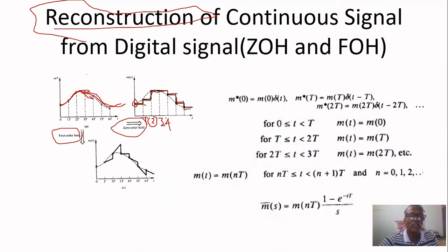If you maintain the same previous value till you get the next value, then it is called a zero order hold circuit. By using that, we converted this digital, discrete signal into an analog signal. So it is a step-like analog signal. For process control, zero order hold is sufficient because the process variable is very slowly varying. That's why it is better to use zero order hold itself.